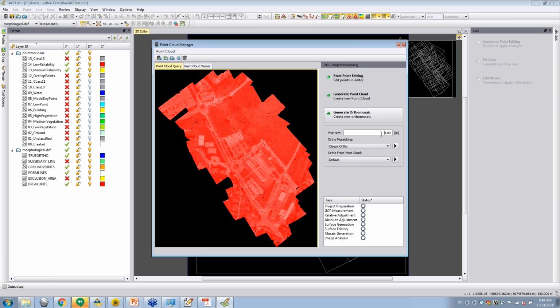So where can I find the ground sample distance? Before you run your project, you would want an idea of the ground sample distance you want when you're collecting data. You wouldn't just slide in an arbitrary elevation, so you would have an idea of that beforehand. But it's also in the camera calibration PDF that we just created, and you can calculate it based on the height of the flight as well as the focal length and pixel size. But you don't need to calculate it. You can go back and look in the PDF again. Okay, so it's in that report. Perfect. And if you set it at the lowest increment, you would just get a resolution based on that, interpolated.